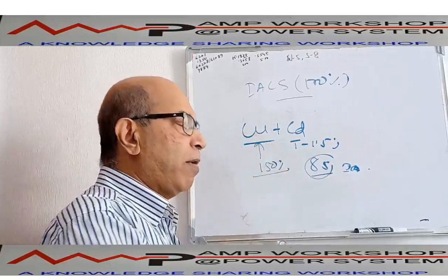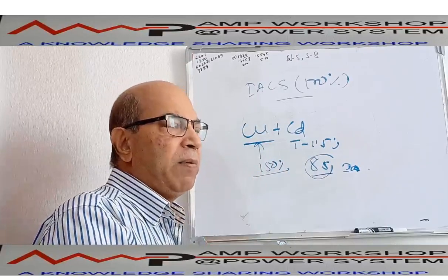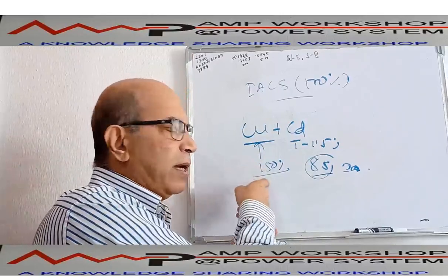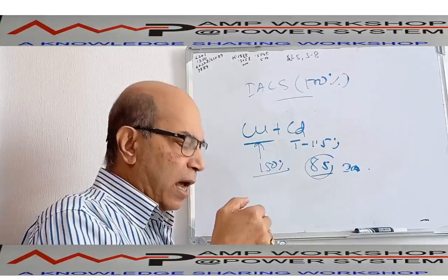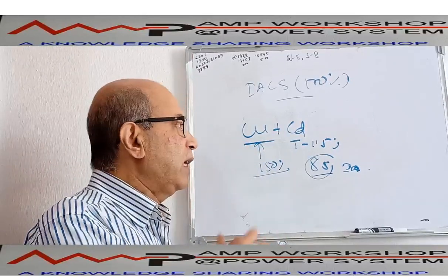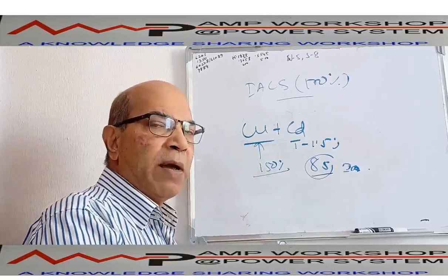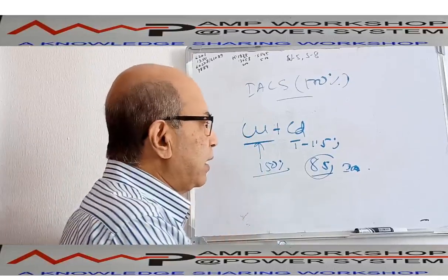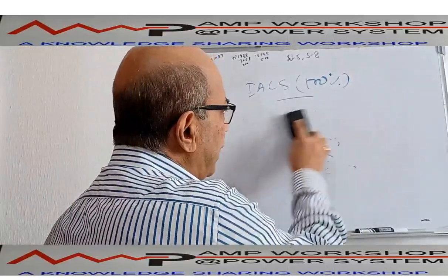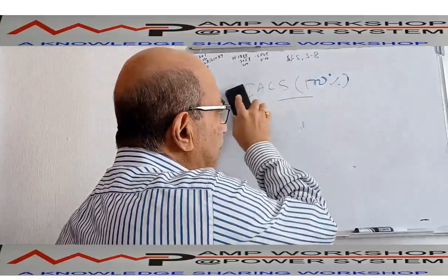And cadmium copper has another application, the breaker contact. You know, for the breaker moving contact, due to high mechanical strength, corrosion and erosion are very low. So in the breaker contact, auxiliary contact, in all those cases we can use cadmium copper. So these are the three types of conducting material we can use for electrical power transmission and distribution.